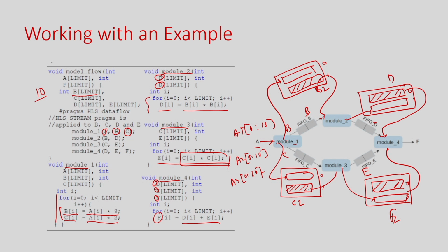So, there is no interleaving happening. You can understand here that it is not that whenever A0 is written, B0 is written, it starts taking B0 and processing. It will actually wait for the completion of writing of the odd or even buffer, and only then will it start. So, by managing this even-odd buffer, or ping-pong buffer, I am implementing this whole process.